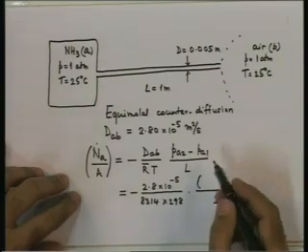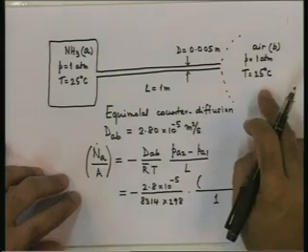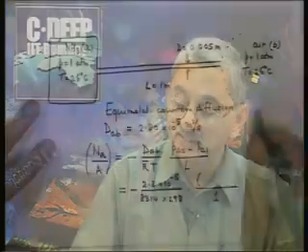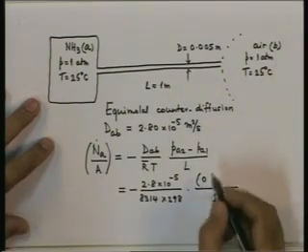Let us assume that there is no trace found of ammonia vapor in the atmosphere. The atmosphere is a large reservoir. Whatever ammonia leaks in gets dispersed pretty fast. That is an assumption. So, the partial pressure of ammonia in the surroundings, that is effectively reservoir 2, will be 0.